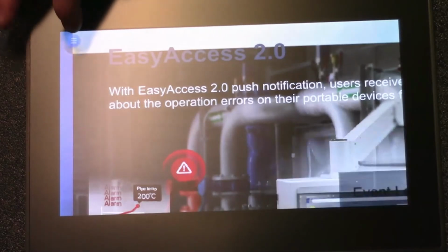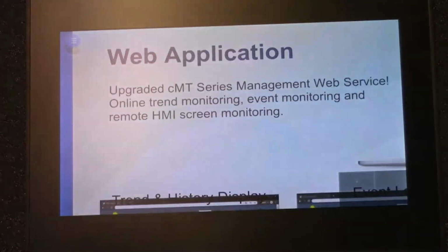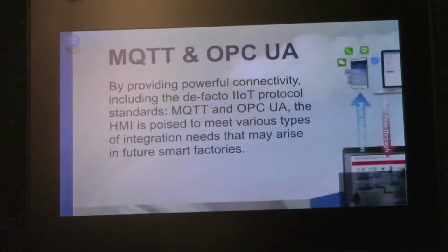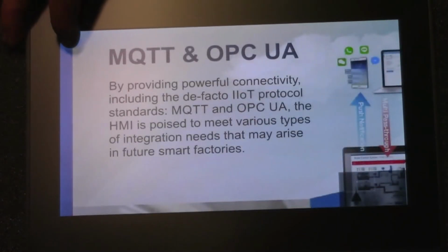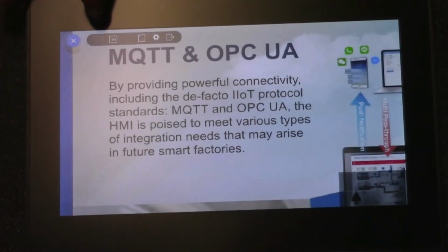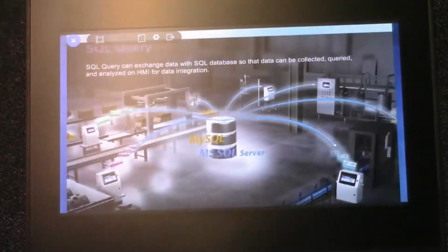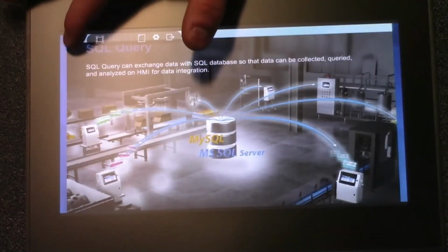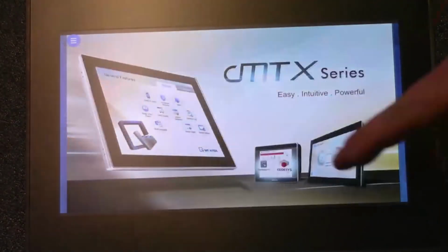That's just because the resolutions of the CMT FHDX 820 are a little different than the 10-inch capacitive screen here. So we're going to click this blue circle and then click this icon on the far left, and that is going to resize our project. So now we are set to the correct resolution.